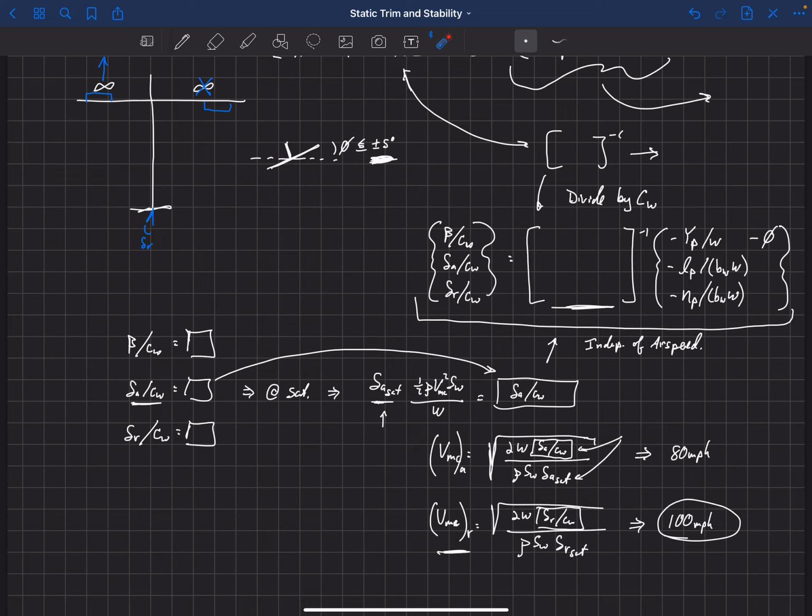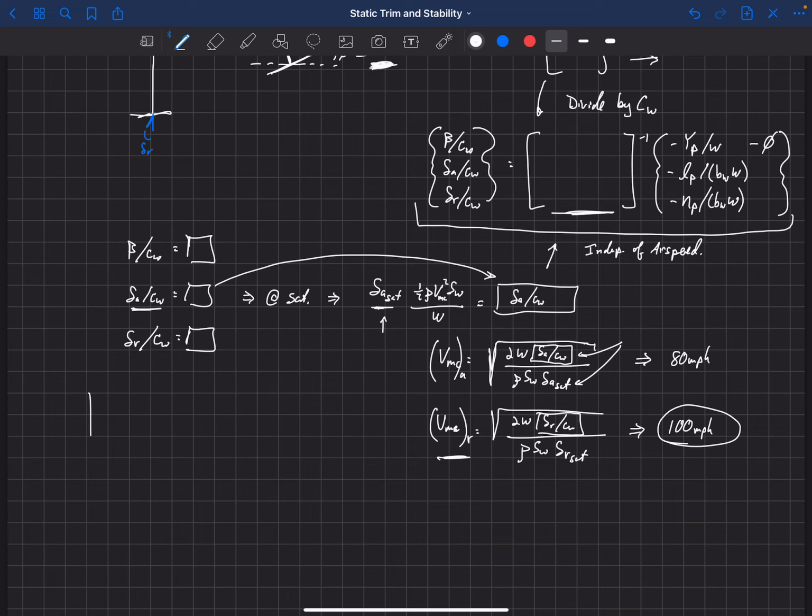That's interesting and comes out of these equations. One other thing you need to be careful about is that we've come up with these values assuming a linear system, within the assumptions of linear aerodynamics. It turns out that control is not exactly linear. Look at, for example, delta A, and we'll put 10 degrees, 20 degrees, and 30 degrees, and then the rolling moment we would get from that.